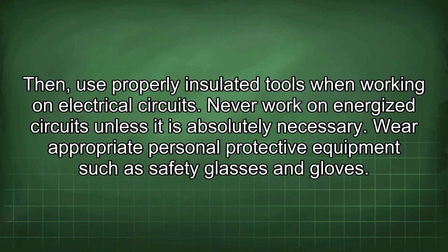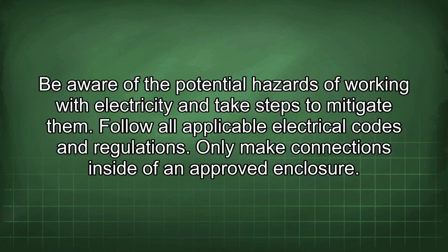Wear appropriate personal protective equipment such as safety glasses and gloves. Be aware of the potential hazards of working with electricity and take steps to mitigate them. Follow all applicable electrical codes and regulations. Only make connections inside of an approved enclosure.